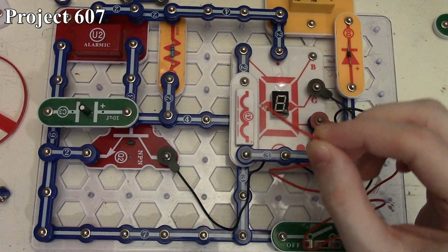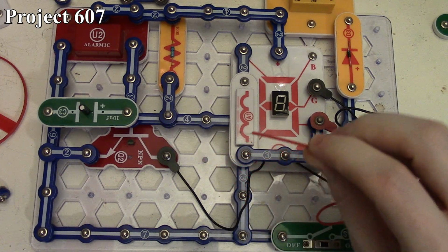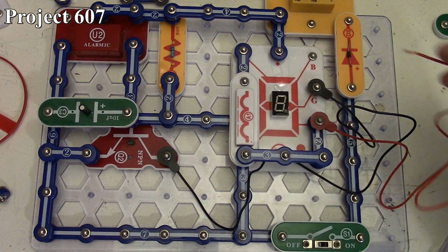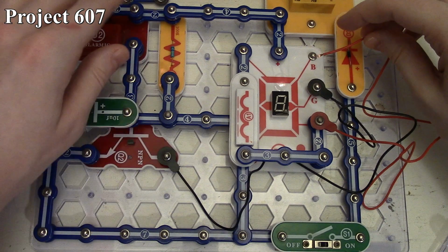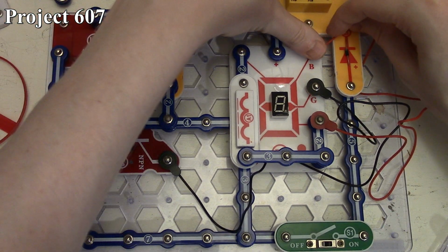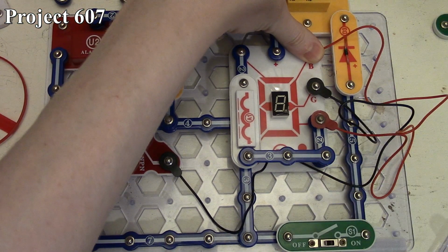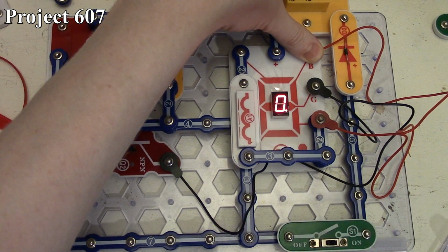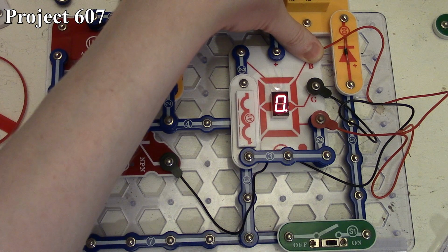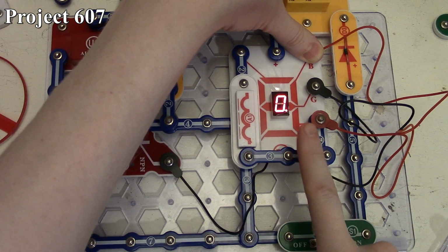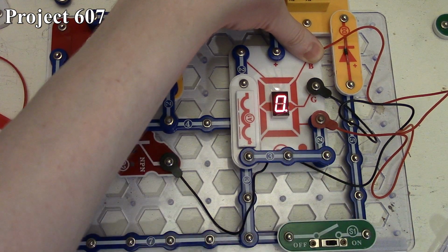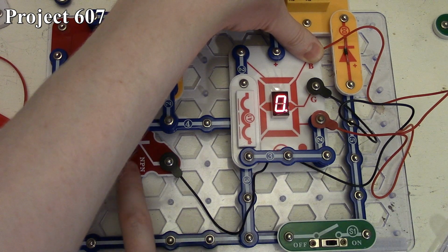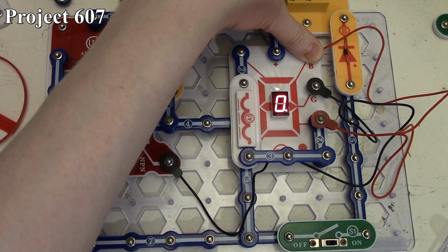Now, I'll admit that my red snap just recently broke, so I just stripped some wire off, so I'm just going to hold it where it needs to be. So again, like the previous projects, we're just changing positions on our 7-segment LED there, so when we turn the circuit on, it will now alternate between showing us a 9 and a 0 as our alarm IC switches our NPN transistor on and off there, changing the segments.